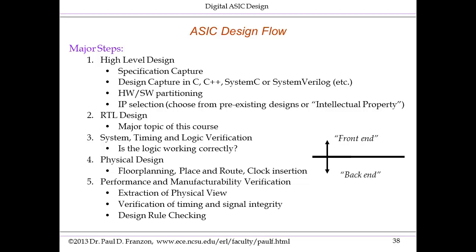So there needs to be a second phase of detailed RTL design, which of course is a major topic of this course. Then of course we want to know that the RTL is correct, so there's a lot of verification that happens, particularly logic verification. Then of course there is synthesis to a gate netlist.